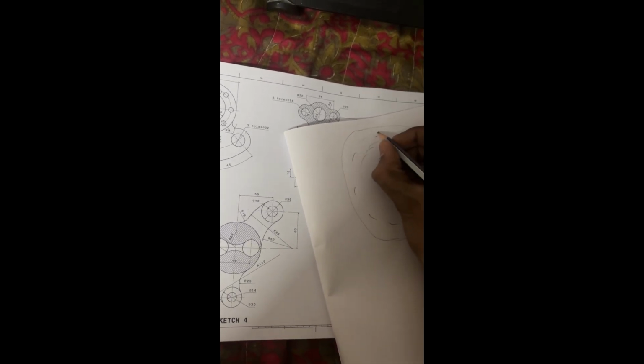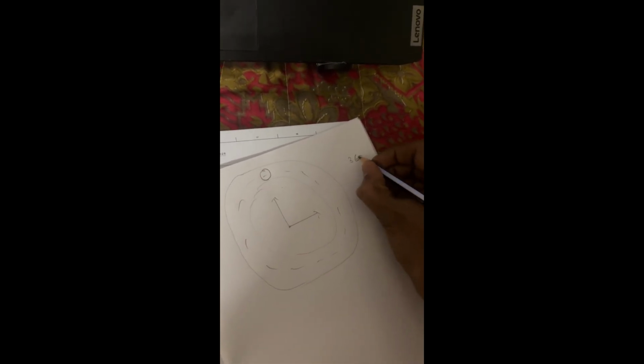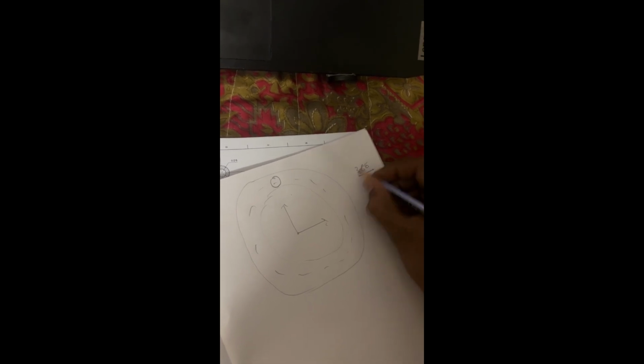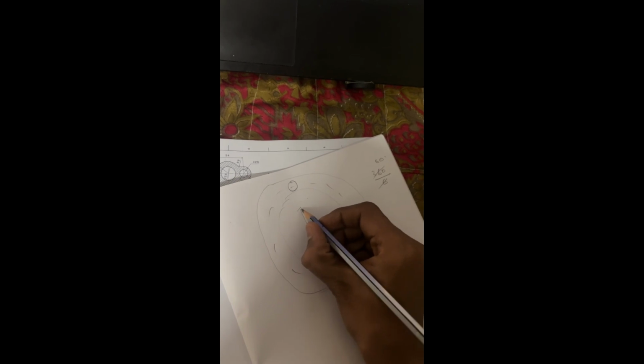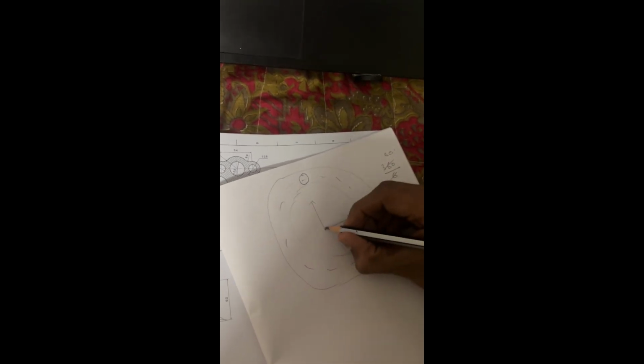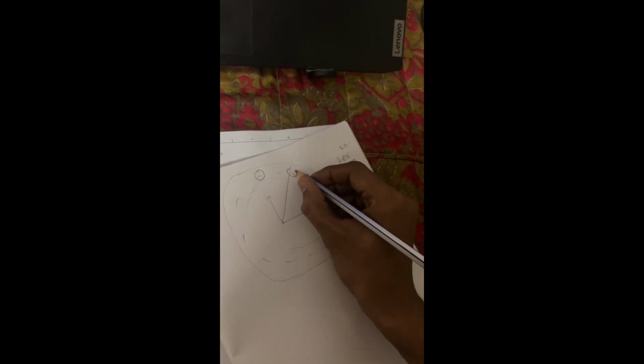And after this we can see that there are 6 circles. A circle is at the top here, and here you can see that there are 6 holes. We all know that for a circle the total angle is 360 degrees. So dividing the 360 degrees by 6, we get 60 degrees. So let us assume that this is at 0 degrees. So this means at 60 degrees, somewhere around here, there should be a second circle, which is here.